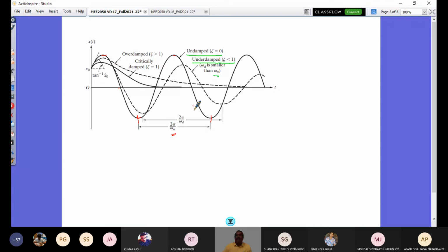Experimentally, I can find out the reduction, or the ratio of amplitudes of consecutive cycles. Or I can take n number of cycles, from one time T1 to T2 with m number of cycles, and take the amplitude at the first cycle till the nth cycle. So I can find out experimentally this logarithmic decrement value, so that I would be able to find out the damping ratio in my system. That helps me to quantify the damping of the system, right?